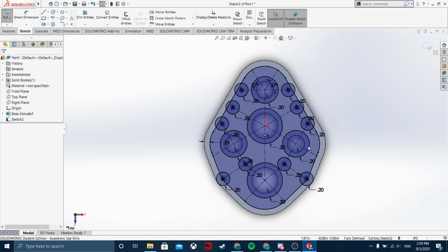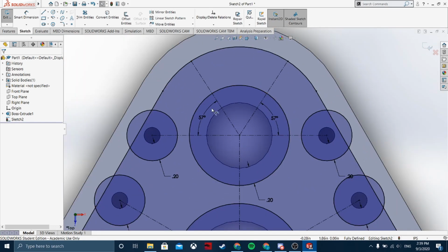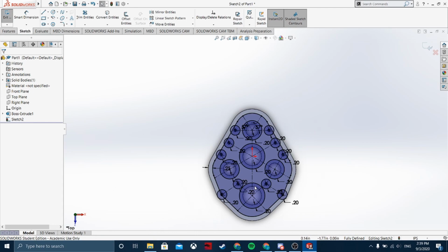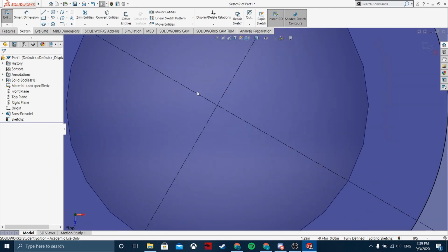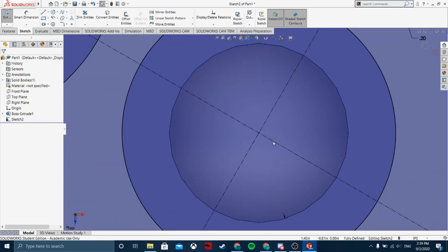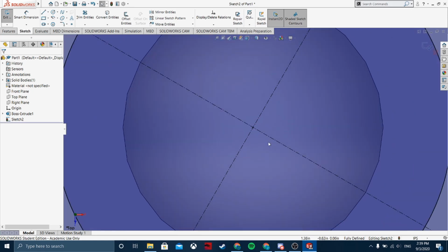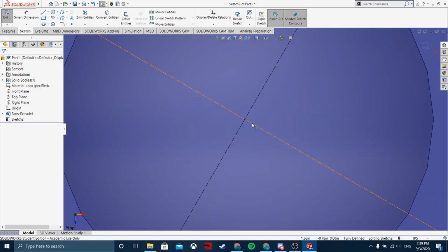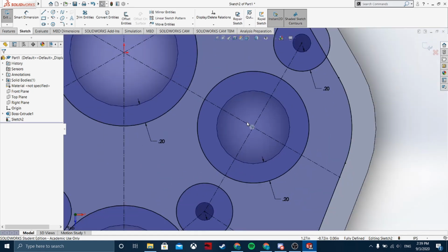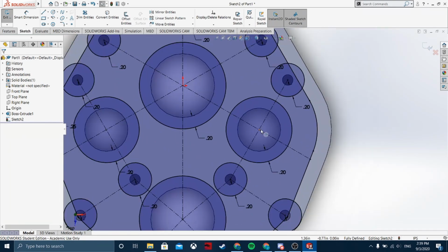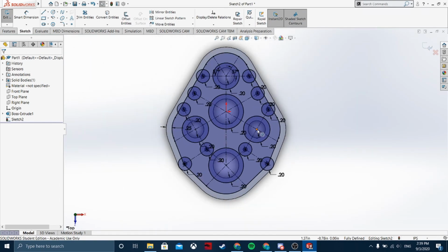Alright, so we have the bridges. For these, I just created two lines and made these 57 degrees each. And for these, these lines were originally undefined, and so I made these lines coincident with this circle's midpoint. Sorry, I mean the center. What am I saying? Okay.